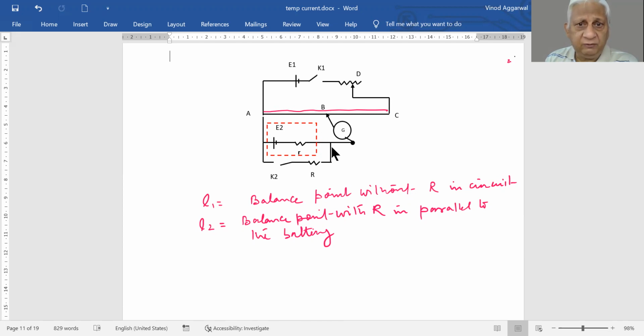And since there is a current flowing in this circuit, r is getting affected. r is playing its role. And that is what we want to do. We want to find the active role of r, meaning find the value of r. So the value of r can only be found if there is a current flow through r. So by putting an external resistance parallel, we are ensuring that some current flows across the battery or across the small r.